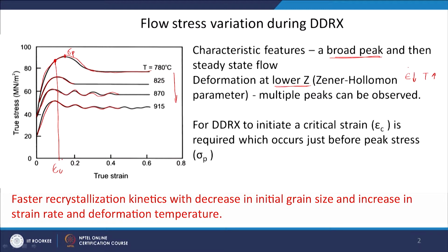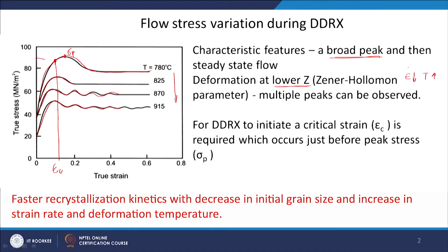So one of the objectives of this lecture is also to find this critical strain or critical stress. The corresponding stress will be your critical stress to initiate the dynamic recrystallization. That we must know as an engineer: what kind of strain I have to impose on the material to start the dynamic recrystallization process.